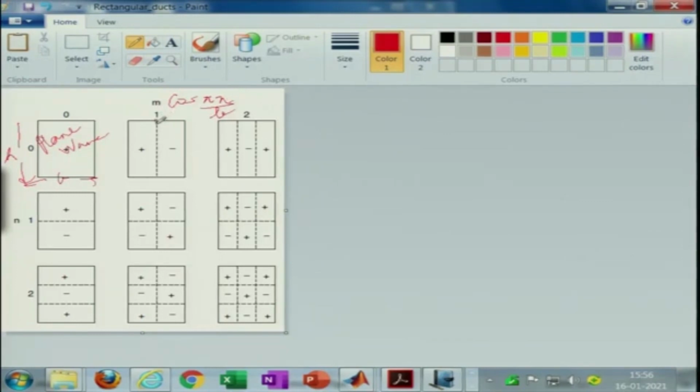What is important here is the nodal pattern, that is the dotted line you see, a line where exactly the pressure is identically 0. Basically that line divides the rectangular cross section into two halves of opposite phases. So, at all times, if you consider a point here and an immediate point here, they will be exactly in opposite phase.